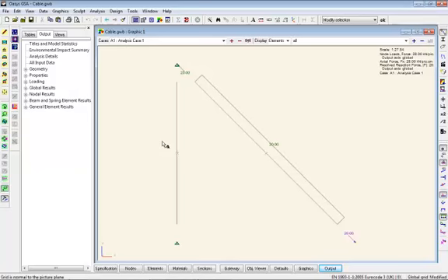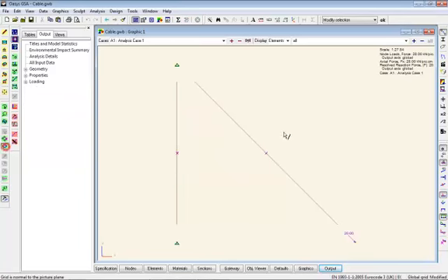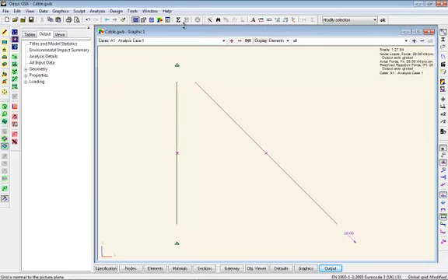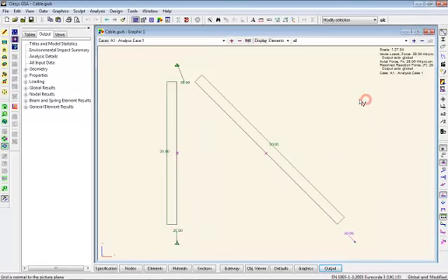And you see, yeah, so the applied load, tension in that tie, and reaction force up there, and because loads are in line with that tie, there's no general deflection on that. Now if we change these ties to cables, and then rerun that analysis, the results we get are rather different.